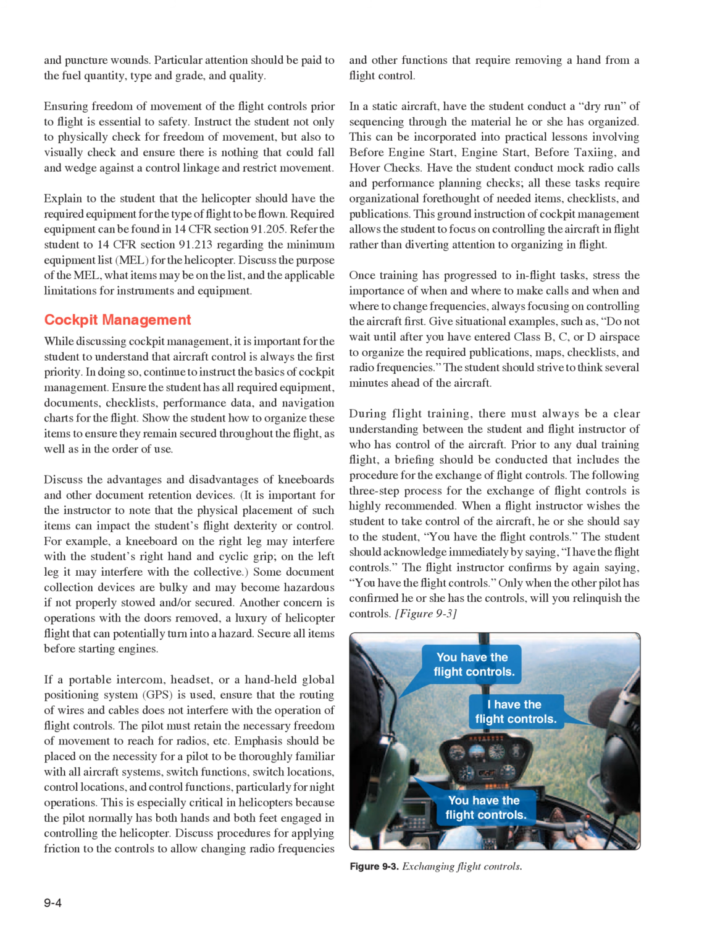Once training has progressed to in-flight tasks, stress the importance of when and where to make calls and when and where to change frequencies, always focusing on controlling the aircraft first. Give situational examples, such as, do not wait until after you have entered Class B, C, or D airspace to organize the required publications, maps, checklists, and radio frequencies. The student should strive to think several minutes ahead of the aircraft.